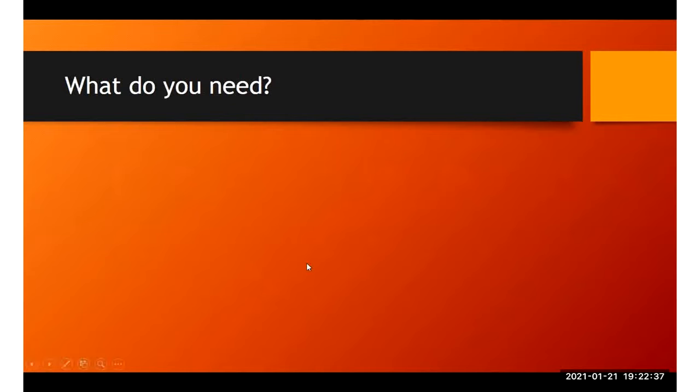Okay, so what do you need? You need a code book. That's a big one. When I offer to help customers do their welder performance qualification testing, one of the requirements is that they have to have a code book when I get there. And I will show them how to use it. I'll go through it with them. I'll do their first initial test with them. I'll talk to them about creating a pre-qualified WPS that meets the requirements of their test. I'll show them how that works. So I'll teach them how to fish. And then if they need any help, I'll bait the hook for them every once in a while. But you've got to have the code book.